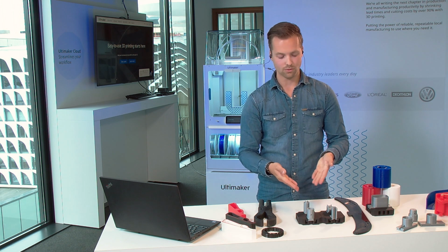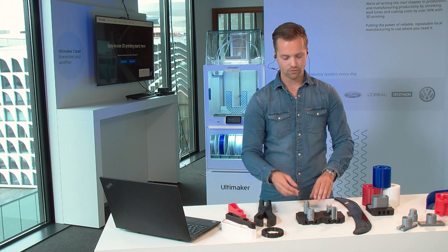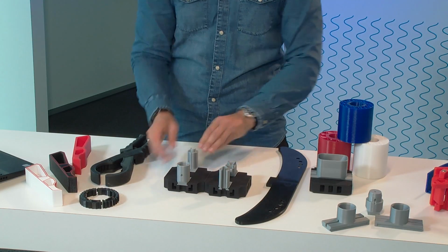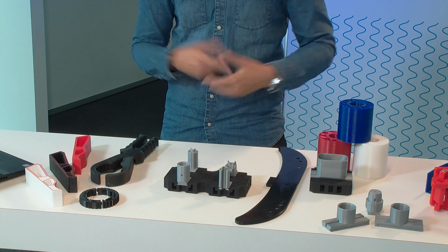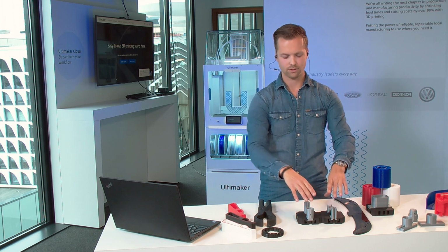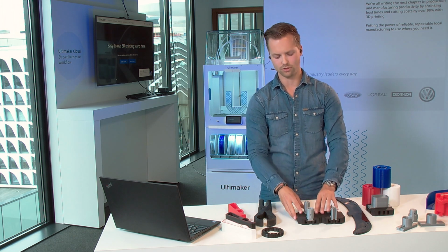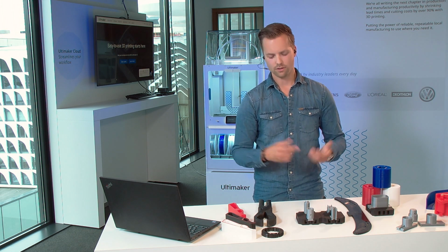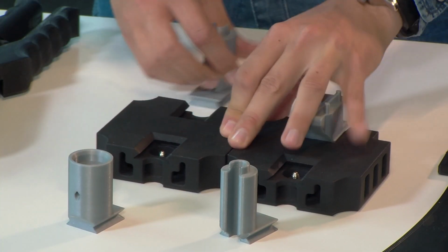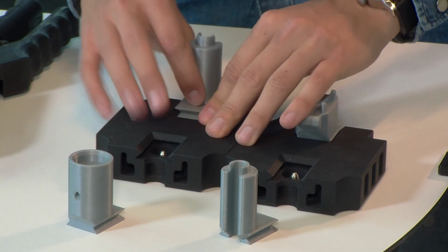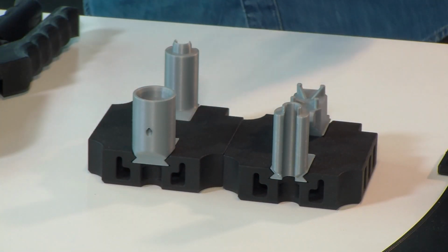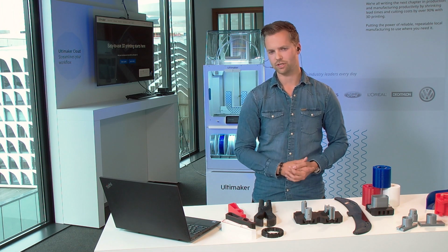It can also be done with this example. If you have, for example, all these silver metallic parts, which you are currently running, and you know you're going to do a changeover in 2 hours, you already gather, for example, your box with inserts in yellow, because you know you're going to run the yellow product. You can stop the production line, quickly remove these parts, get the yellow parts in, click them in, especially for this modular system, it's really easy, and then run production again. So then you have a fast changeover.